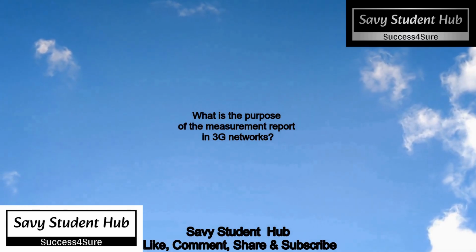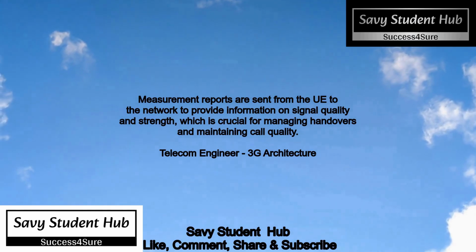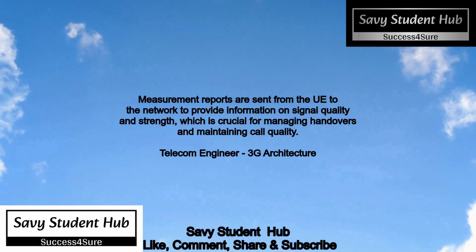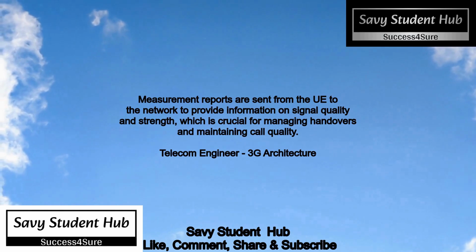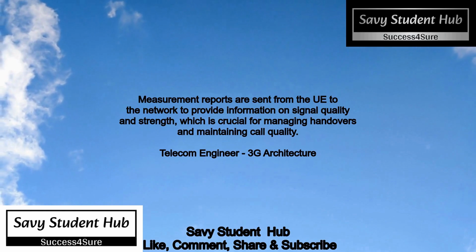What is the purpose of the measurement report in 3G networks? Measurement reports are sent from the UE to the network to provide information on signal quality and strength, which is crucial for managing handovers and maintaining call quality.